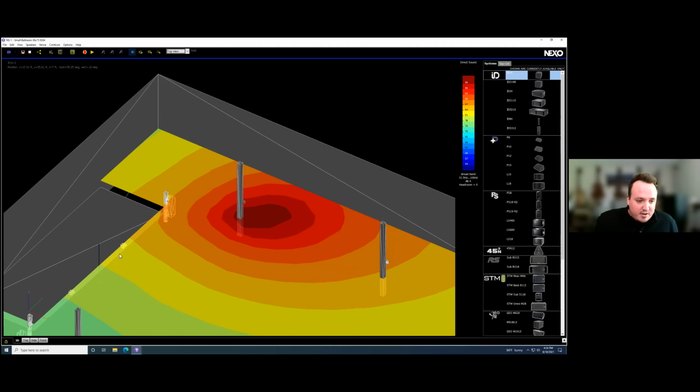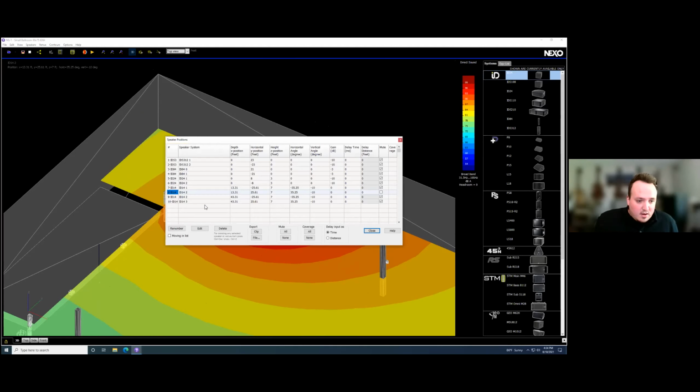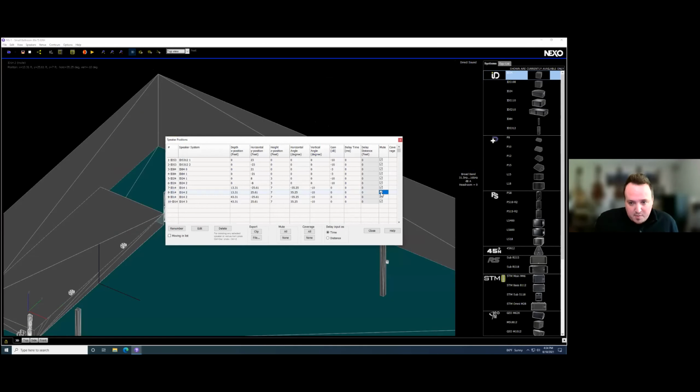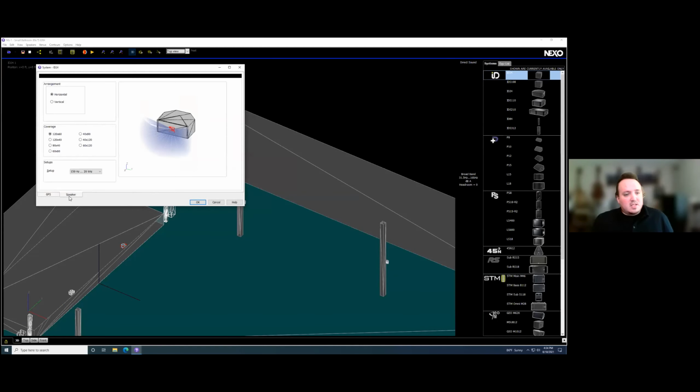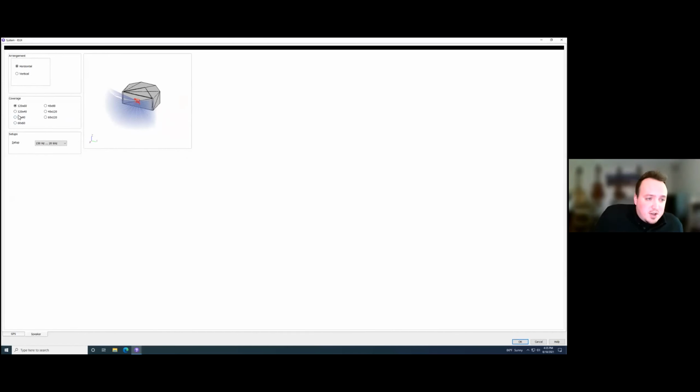And then kind of same scenario going on with this ID24 speaker up front. So many of you are familiar with the concept of front fills. The ID24 is another one of those problem solver speakers. It has an incredible output for its size, which you saw earlier on the specs that David shared. But one of the even more important things to note about the ID24 is the sheer amount of flexibility it has in those HF directivity options. So as you see here in a front fill scenario, I'm using this as 120 degrees horizontal by 60-degree vertical to just cover as much space as possible.